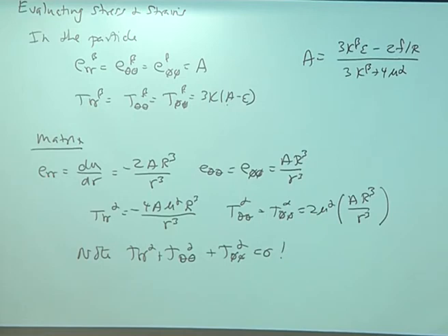Mechanical stress equal to 0. There are lots of generic, interesting problems associated with this. So let's look at T theta theta. This is the stress in the theta direction, parallel to the interface, as you go across. So T theta theta, theta plane, theta direction, is tangent to the interface. It varies with position outside the particle, and once you go inside the particle, it's a different value. If you evaluated this at capital R, those would cancel, and it would be 2 mu times A.